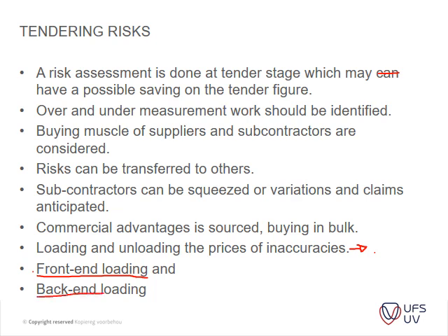And then obviously you get back-end loading, where you load some of your items at the back of your project. That might be, for instance, your finishes, etc. If you anticipate that it will assist you, or if you can get certain items at a better cost, it might benefit you to load some of your items at the end of your project. Or when you foresee that your cash flow might be low at the end of the project, you can load some of the items there.